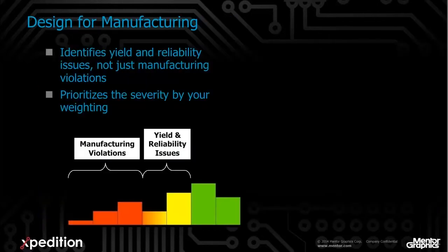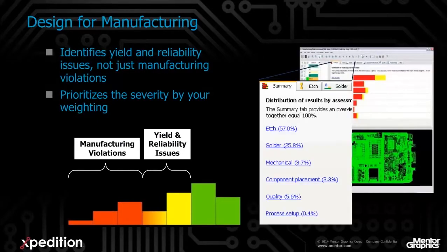After applying the manufacturing process rules to the model of your PCB, the manufacturing process hazards are presented back to you according to the severity and the manufacturing process that has a compatibility problem with the product as currently designed. Notice that the DFM analysis results are not presented as go, no-go like design rules checking. Manufacturing process is all about percentage yield and degrees of quality and product reliability.